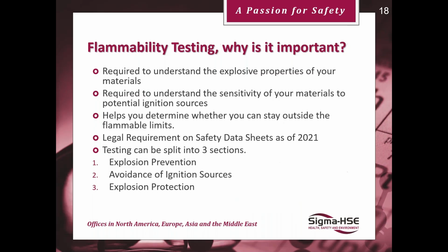So why is flammability testing important? Well, you need to understand the explosive and flammability properties of your materials. How can you pick a basis of safety unless you know how the product behaves? It's required to understand the sensitivity of your materials to potential ignition sources, especially if you're looking at avoidance of ignition sources.